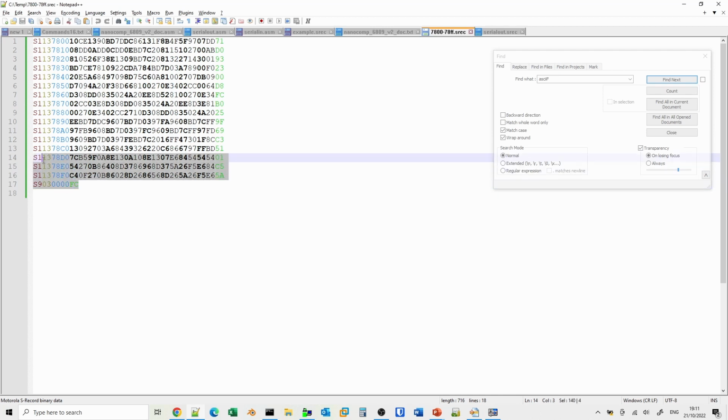So there was a minor problem, but it just shows that with the zero insertion force sockets, we can make changes quite quickly. Now the only thing I would say is you probably want to put the EPROM programmer in the same orientation as where the chip goes, otherwise you may switch them around.